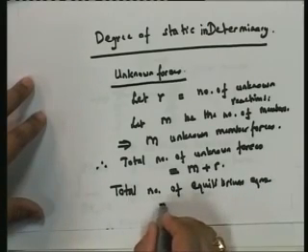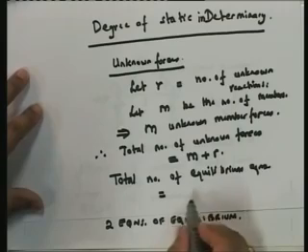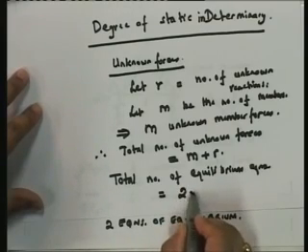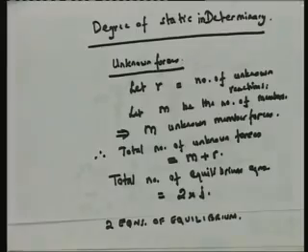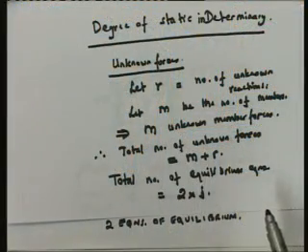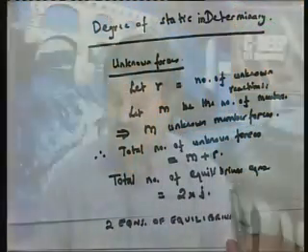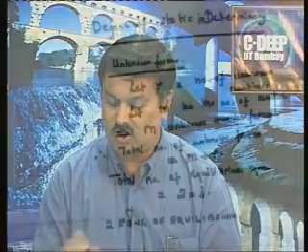Well, they have to be equal to 2 into the number of joints that you have in the structure. So, I am defining J as the number of joints that you have in the structure. Since you have 2 independent equations of equilibrium at each joint, the total number of independent equilibrium equations is 2J.